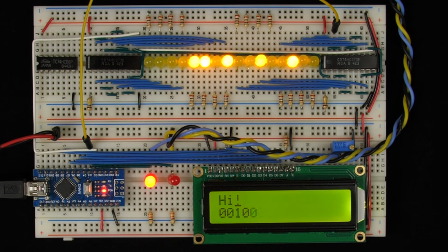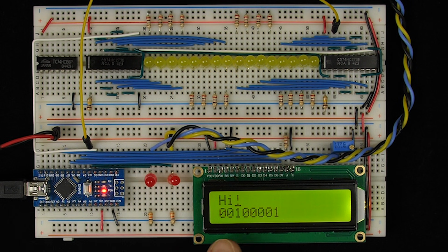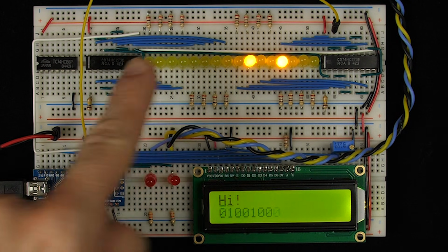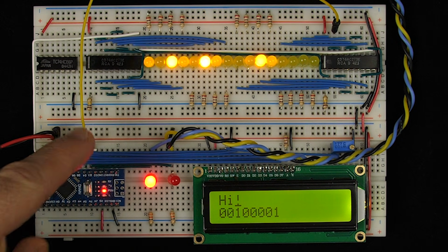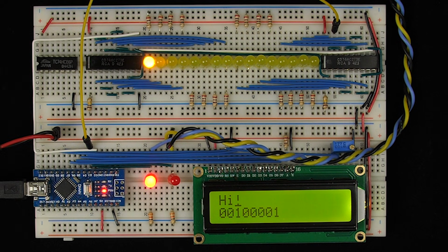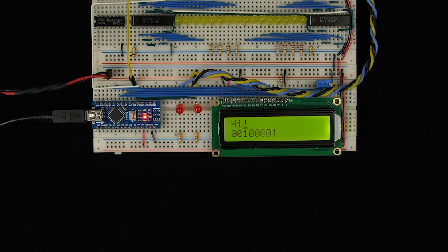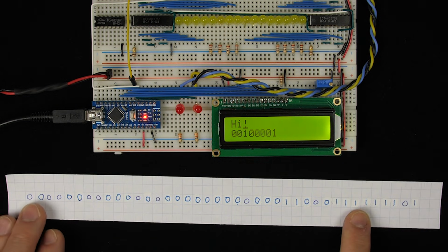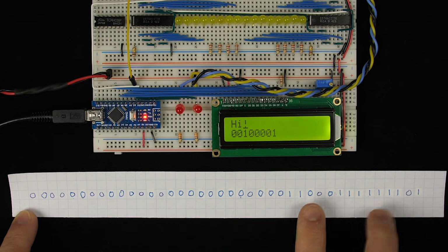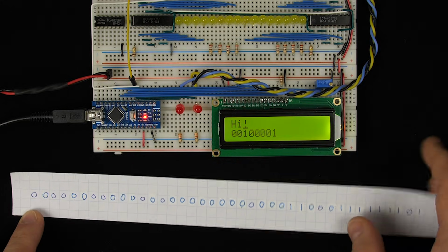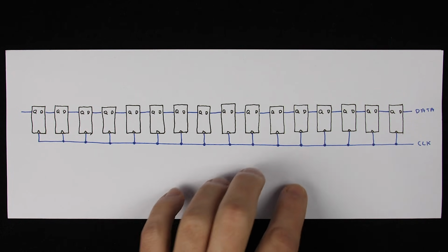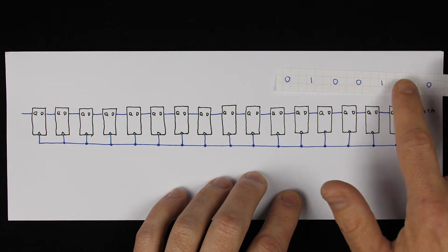It's sending "hi", and now it's sending a bunch of zeros. So that looked like it worked, and we can reset it just to make sure, but there's our H, there's our I, there's our exclamation point going across, and then it just sends a bunch of zeros. So that's what we want. Because remember, that was originally what we had on this piece of paper here: we had our message here, and then we had zeros over here, and once we run it through our little algorithm, we'll get our CRC over there.